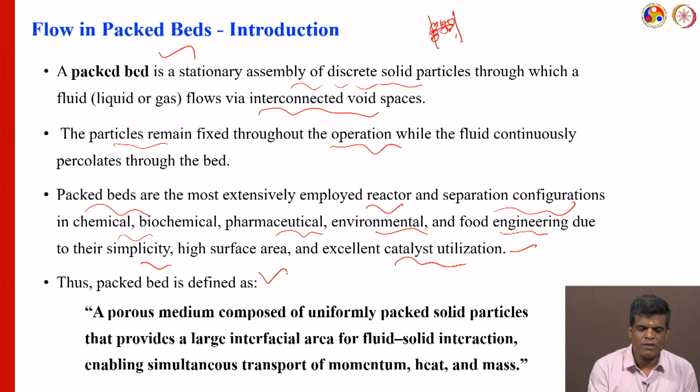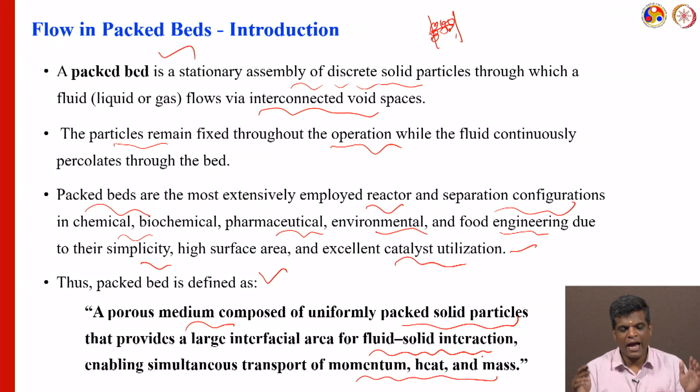So that's the reason a packed bed is always defined as a porous medium composed of uniformly packed solid material, solid particles that provide a large interfacial area for the fluid-solid interaction, so that we can enable the simultaneous transport of momentum, heat, and mass. In the packed bed system we can do heat, mass, and momentum all three together. There is heat transfer taking place, and mass transfer also, and momentum transfer also. So all types of transfer take place inside the packed bed.